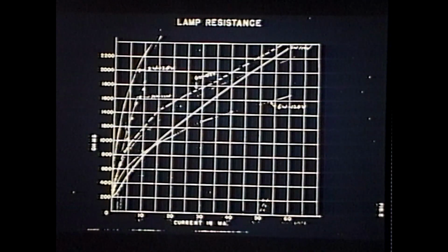This is a figure from Hewlett's thesis. What he's playing with here is which light bulb to use. And what he's trying to figure out here is, here's the impedance of the lamp versus the current through it. So he's looking at the resistance versus current curves of various lamps. And obviously, as you move up in this direction, the gain of your gain control goes up. He's trying to figure out where to park it here. He's screwing around with various light bulbs. Doesn't look like he modeled it in SPICE based on the plot here.